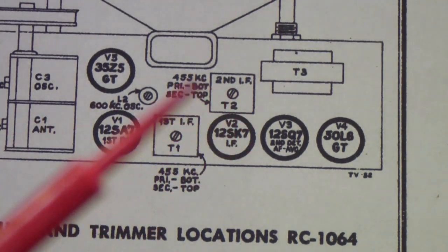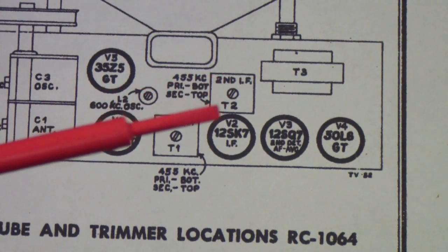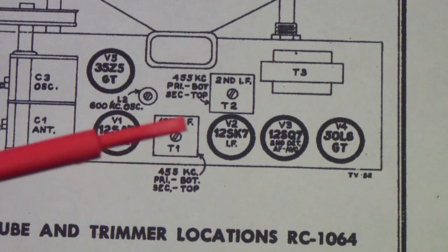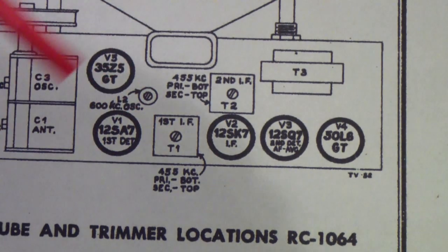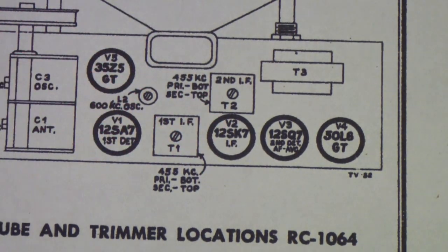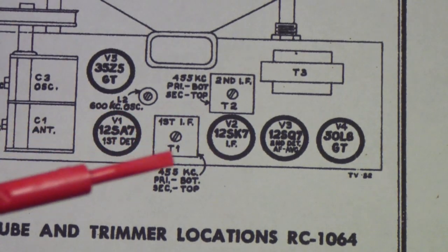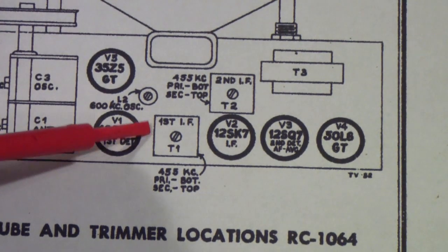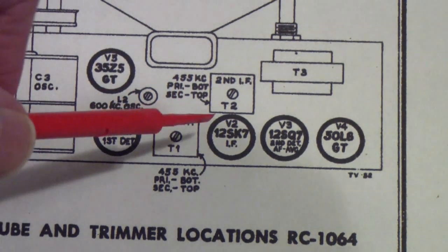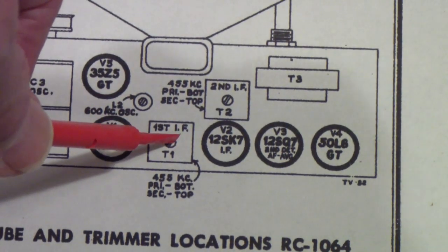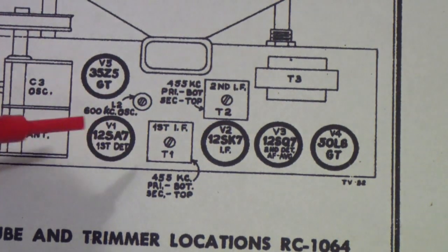Now, for a couple of reasons, you probably want to get a set of alignment tools that will work with your radio. You notice this is a fairly small screwdriver tip. It's made out of plastic. On the other end is a larger one. There are two reasons you want to use these kinds of tools. First, because they don't react with the circuit. In other words, if you used a magnetic material like a regular screwdriver, when you put it down inside the IF transformer, the screwdriver itself is going to affect the tuning.